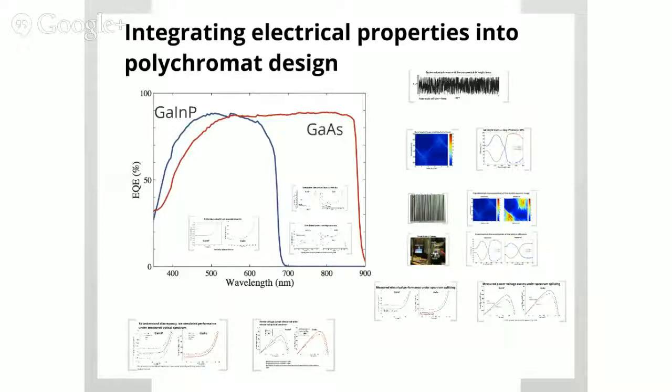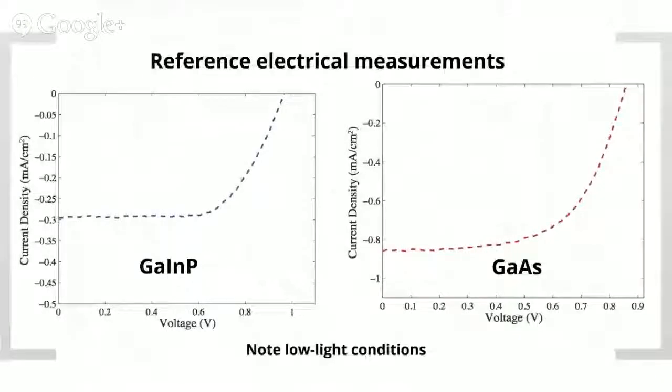That's it. So the reference measurements were done. We have seen this before. Basically, for gallium indium phosphide, gallium arsenide, essentially we just use white light, simulated white light, not the sun. And you can see the current density versus voltage. The current density, first of all, you'll notice is very low because my illumination is extremely low, as I told you before. Same thing in gallium arsenide, gets slightly higher, gives a lower band gap, the photons. The current density is more than gallium indium phosphide.